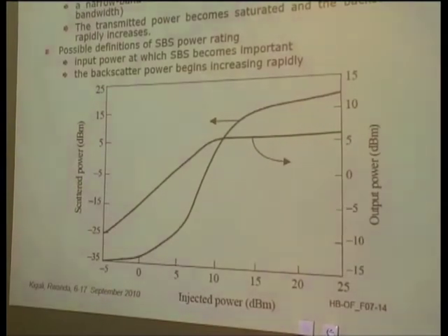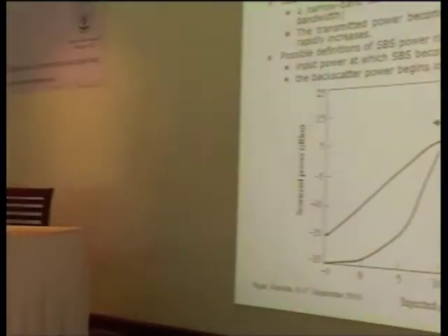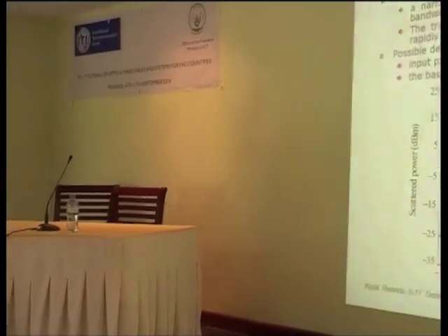The important thing is that if you want to input large power into the fiber, simply speaking, you may increase the signal bandwidth of the transmitted power to reduce the stimulated Brillouin scattering. Fortunately, we will have 10G systems or 40G systems, so the signal is modulated, not a single spectral line, but modulation causes spectral broadening, at 10G or 40G. So signal power will be spread along the bandwidth of the transmitted signal. So we can effectively reduce the stimulated Brillouin scattering. So nowadays, this SBS is not so problematic in actual optical amplifier systems.